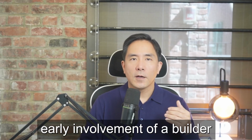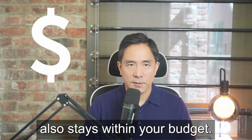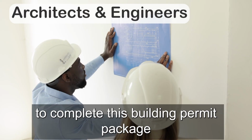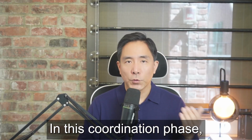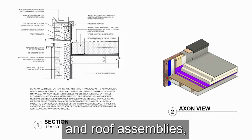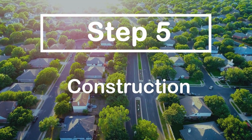Oh, by the way, early involvement of a builder is also very beneficial because it's crucial that your dream home design also stays within your budget. Early involvement of a builder can solve this issue. Sometimes a builder coordinates with an architect and engineers to complete the building permit package and submit it to the city. In this coordination phase, we also provide more detailed drawings. This includes foundation, exterior wall, floor and roof assemblies, connection details, and other drawings to aid in the construction of the project.